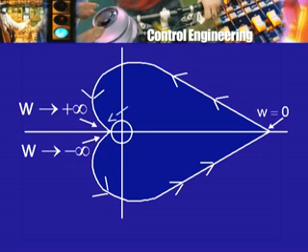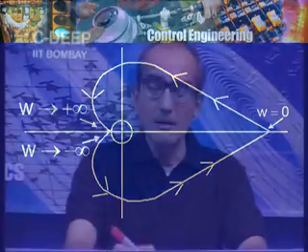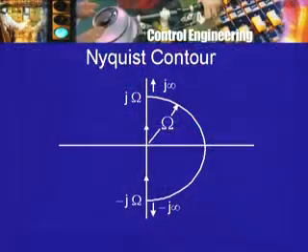Well, this upper part corresponds to omega tending to infinity, so the lower part will then correspond to omega tending to minus infinity. In other words, one end of it corresponds to this point on the Nyquist contour, the other end corresponds to this point on the Nyquist contour. But these 2 points are not the same point, they are separated. Although one of them is j omega with omega very large, say 10 raised to 5, the other is minus j omega with the same large value, minus j 10 raised to 5, but this is not quite the same thing as j infinity and minus j infinity.